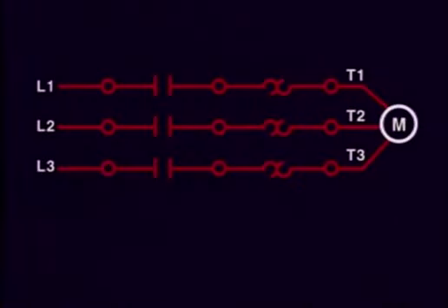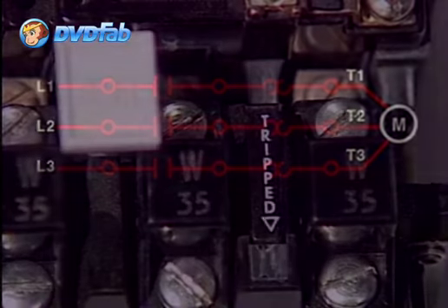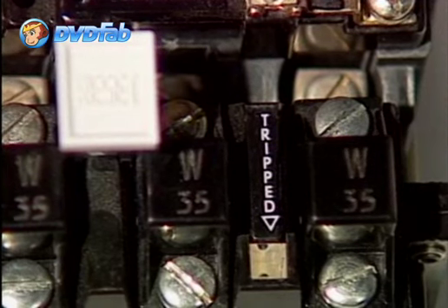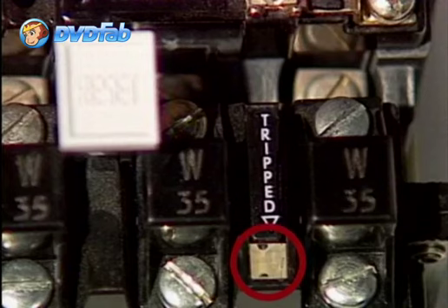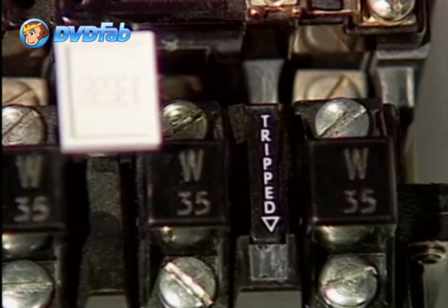If the contacts are working properly and supplying the proper voltages, then you should check the overloads. In fact, in a motor control circuit, if the motor was running and stops, the first thing that you should check is to visually see if the overloads have been tripped. This is usually available at the starter, where an overload trip indicator can be visible. If this is the case, you should wait a couple of minutes and reset the overloads and start the motor.